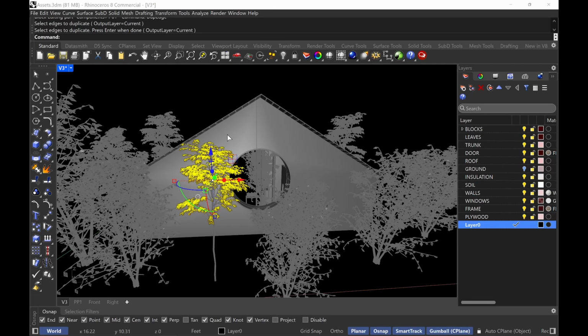And I'll show you a different setting, similar to the previous video of the monochrome section perspective, where it's just the actual monochrome display style setting. I recommend doing this before you start duplicating the blocks everywhere, because it'll take a much longer time to apply to all of them. So I recommend doing it when you first get the block. And if you don't like how the curves look in the display style, then just turn off that layer. Don't do it later on, because it'll take up a lot of time. It will take up a lot of memory.